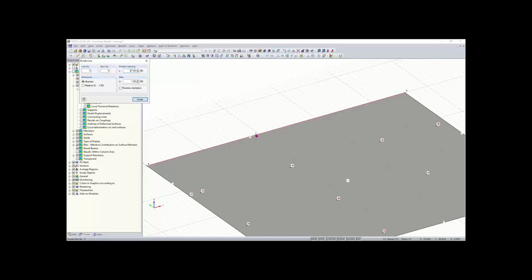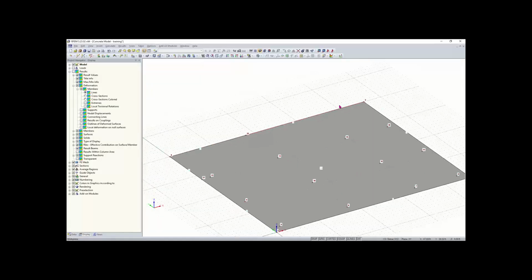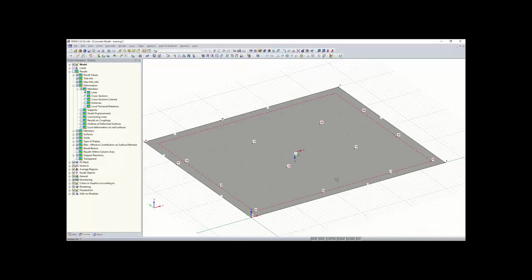I'm going to place it right here. This is going to be 28 feet from the start. So I'll place that, and now you can see that we have 2 lines now with the node there placed at 28 feet from the start. And also again, if you're confused about the orientation of your line, you can see the arrow here. When you hover over your line, this red arrow tells you the direction.